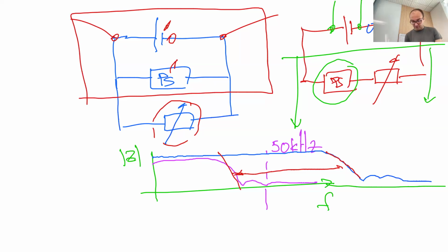cell. Because if it's vice versa, let us assume that we bought a wrong power supply, and the power supply has a frequency characteristic like this. When we start exciting our fuel cell, in this part here we will see the response of the fuel cell, but from this point onward, we're going to see the response of the power supply and not of the fuel cell itself.